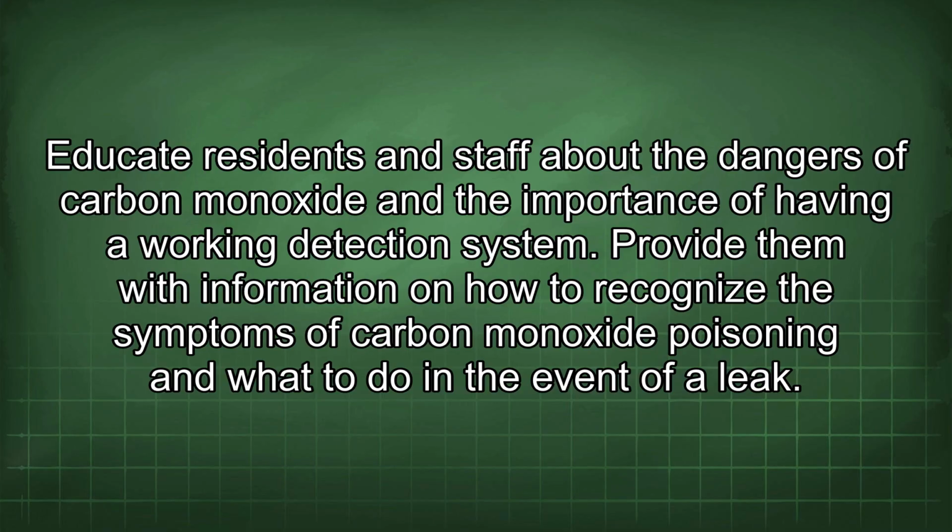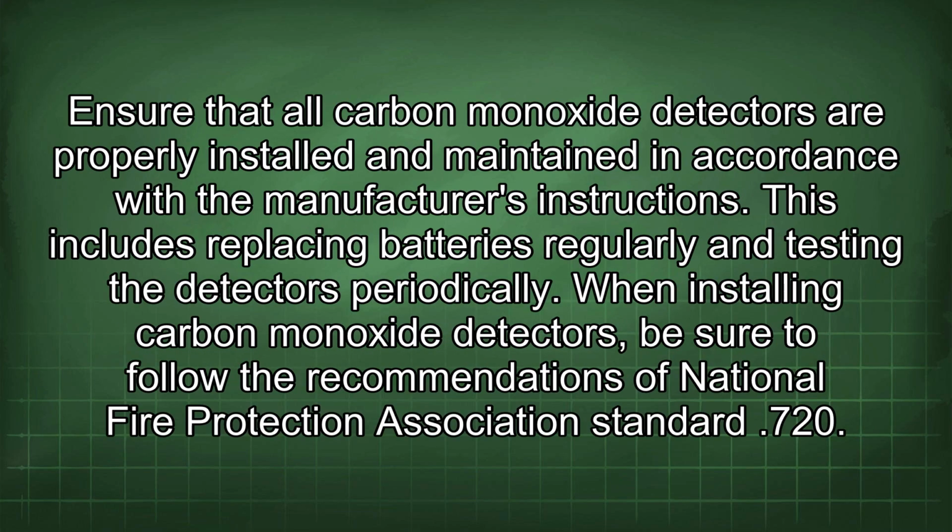Provide them with information on how to recognize the symptoms of carbon monoxide poisoning and what to do in the event of a leak. Ensure that all carbon monoxide detectors are properly installed and maintained in accordance with the manufacturer's instructions. This includes replacing batteries regularly and testing the detectors periodically.